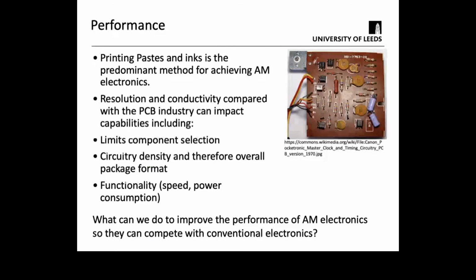When we look at the performance of 3D printed electronics, you could arguably say it's like going back to the 1970s in terms of the capability. If you don't have the same conductivity of the conductor level, if you can't get the same fidelity in terms of resolution, then you're limited by the types of components you can package, the density of the boards. So therefore, what you do is you end up using larger components. Also, some of the materials that are used are typically low temperature materials.